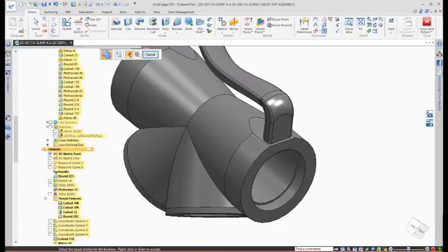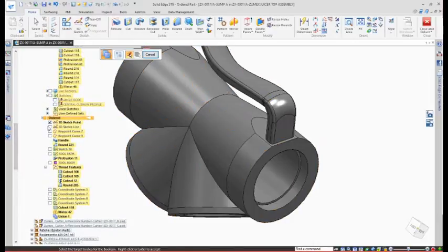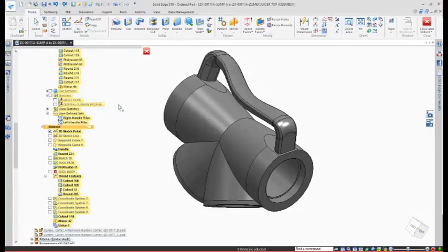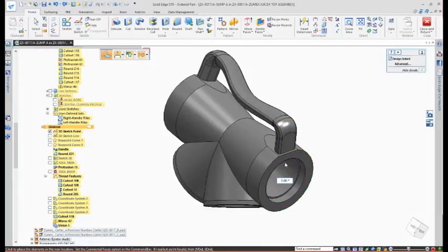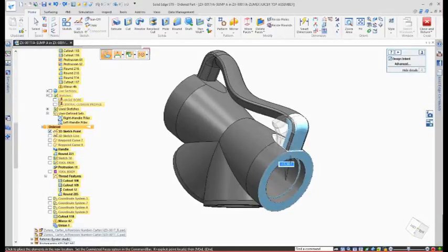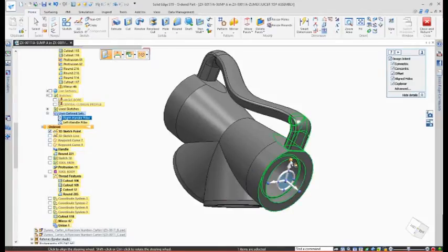Let's take, for instance, this handle. This handle is not quite the distance that we want it to be. In our case here, what we need to do is make some modifications to the handle. The handle itself probably needs to have some rotation done to it. I want to go ahead and click on this right hand handle as a defined set and make some adjustments. I'm thinking something like 20 degrees. Maybe negative 20. That looks better.